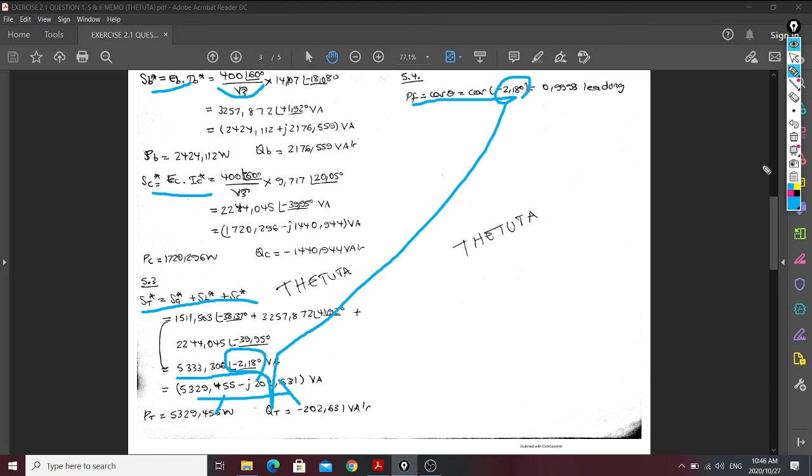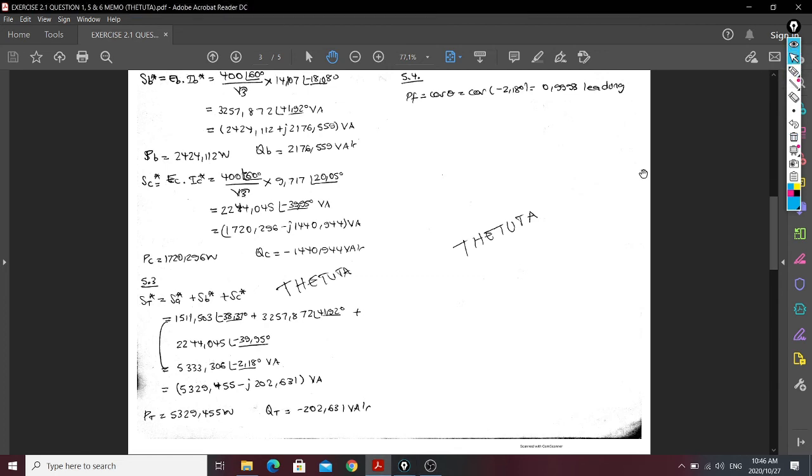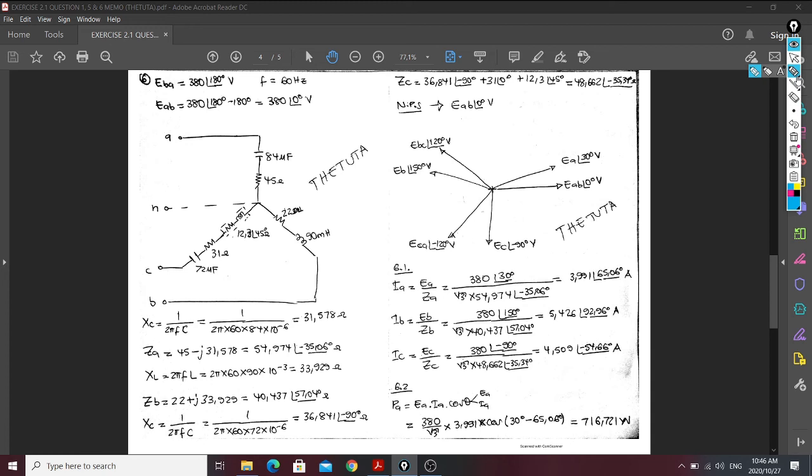Simple and straightforward. Again, we're going to have a look at question 6, which is the last question under the load circuit, and they give us a combination of a resistor and a capacitor. This means we need to get their total impedance. We change the capacitor to capacitive reactance, so that we can get our ZA in branch A, which is a combination of a resistor and a capacitor.